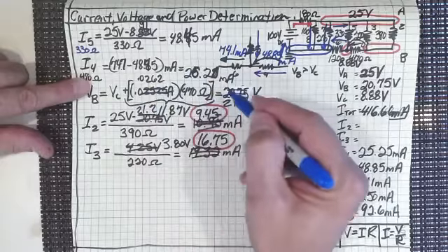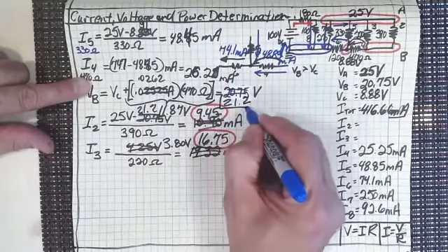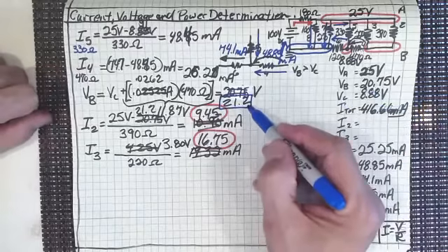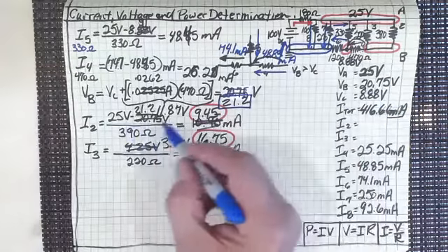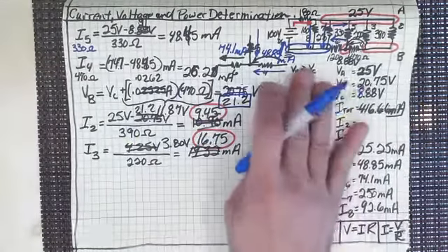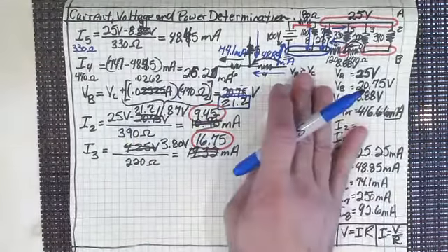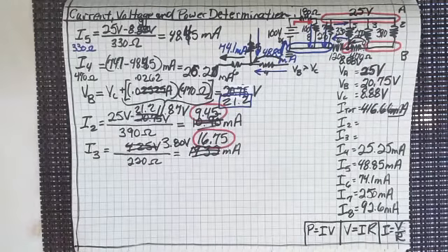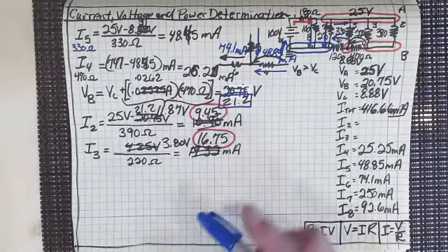And so I placed that back in here, and I found out that our voltage there actually isn't 20.75, it's 21.2. And in fact, I only found that I had lost like 5 milliamps in all of the analysis that we had done. But I thought, well, that's significant. And in fact, I found out that no, it was just propagation of calculator error, because instead of using 5 significant digits, I only used 4 significant digits at most places.